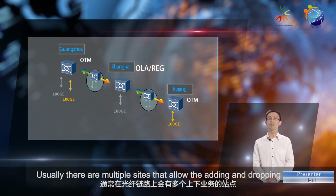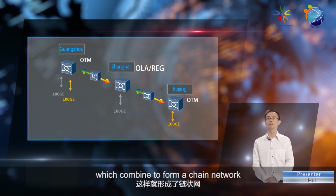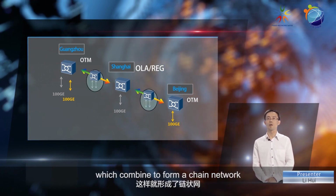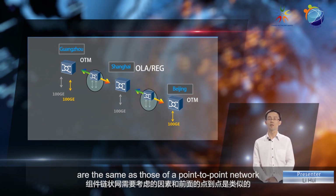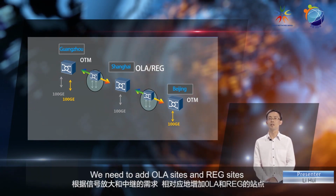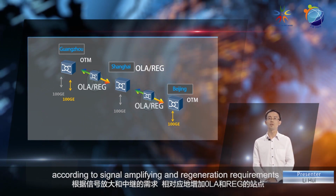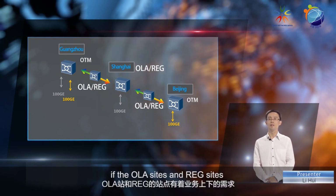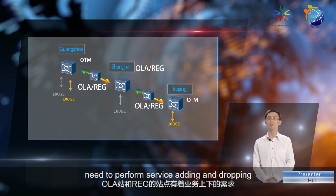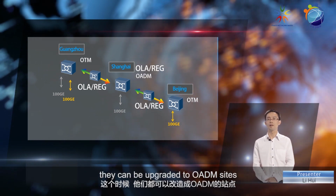Usually there are multiple sites that allow the adding and dropping of services on optical fiber links, which combine to form a chain network. Factors which need to be considered in a chain network are the same as those of a point-to-point network. We need to add OLA sites and REG sites according to signal amplifying and regeneration requirements. As the service develops, if the OLA sites and REG sites need to perform service adding and dropping, they can be upgraded to WDM sites.